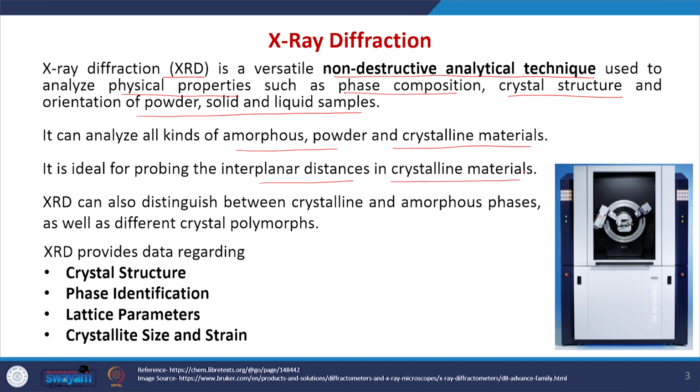Interplanar distance means the distance between any two parallel planes in the crystal. XRD can also distinguish between crystalline and amorphous phases as well as the different crystal polymorphs. And XRD provides data regarding crystal structure, phase identification, lattice parameters and crystallite size and strain.